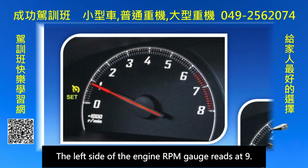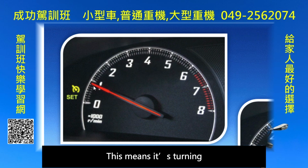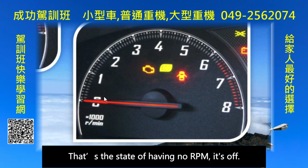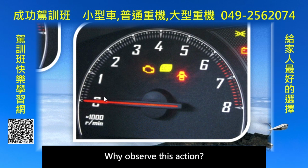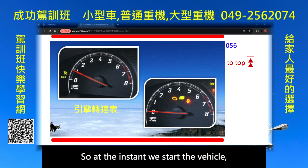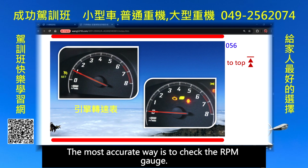The needle on the engine RPM gauge reads at 9. This means it's turning. 900 RPM, the engine is running. The gauge below shows 0 RPM. That's the state of having no RPM, it's off. Why observe this? Because if the engine is already running when you start the vehicle, the starter motor can easily break. This is a reminder for everyone. So at the instant we start the vehicle, we must confirm the engine is running. The most accurate way is to check the RPM gauge.